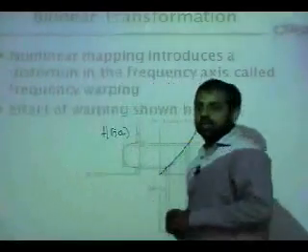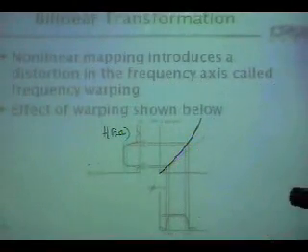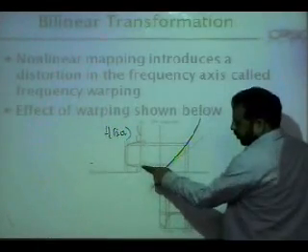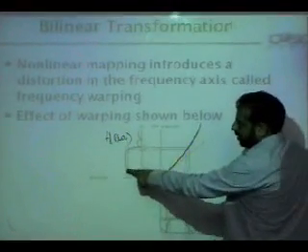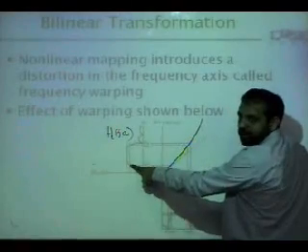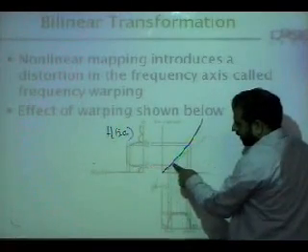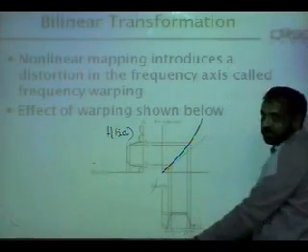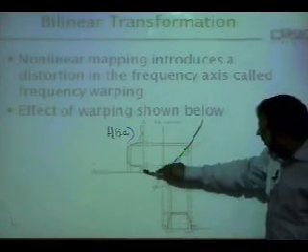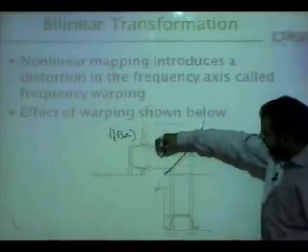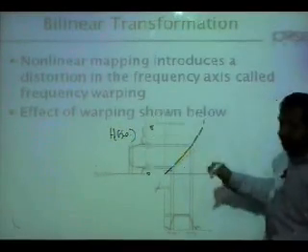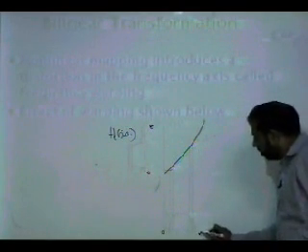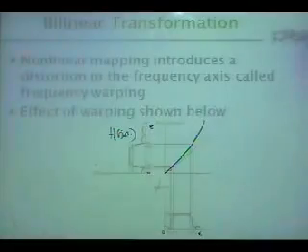As I mentioned earlier, if you are computing, go to a value of omega, find out the Hc j omega, and now translate it into small omega. It is guaranteed this whole thing will lie between minus pi and pi. If it goes from 0 to infinity, it is guaranteed that this whole thing will run from 0 to pi.